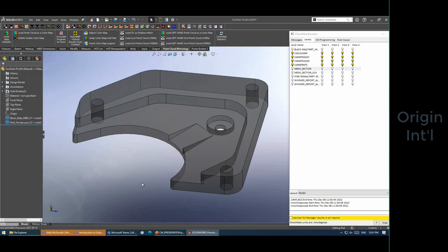Well, that's how it used to be, right? That's car body, right? Yeah, that's how we used to do it before we got into GD&T. It still exists. When I was working for the truck interior manufacturer, plastic injection molded, all those parts, we had to keep them in truck body coordinates when we were inspecting them. And the datums, well, they have a full set of datums, but the master locator was truck body zero.